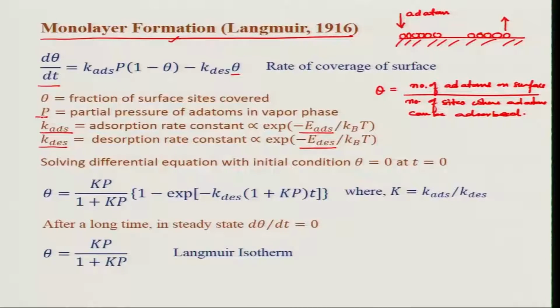So, if there are more adatoms in the vapor phase, they are more likely to cover the surface of the substrate. Now, desorption will depend on how much is covered, because no atom can be desorbed from an empty site. So, it depends on how much is the fractional coverage, theta, while on the other hand adsorption depends on the empty sites, 1 minus theta, and what is the partial pressure of adatoms in the vapor phase.